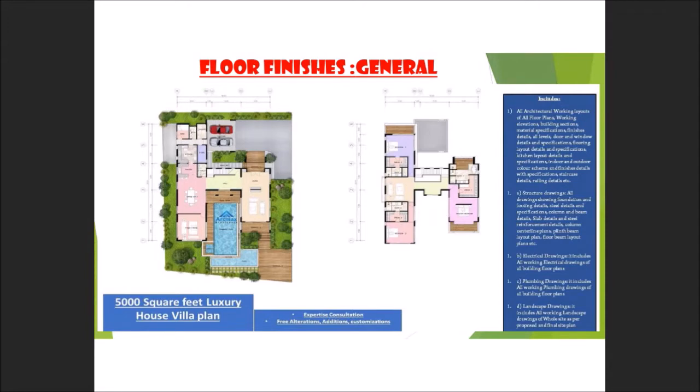When we talk about specification, we always refer to the materials. This is something that you have to understand, and you also have to write down in the description. Material, and the size, which refers to the dimension of that particular tile, parquet, and so on. For example, for tiles, you can see maybe 100 times 100 times maybe 8 mm thick. So this is the length, width, and thickness of the tiles.